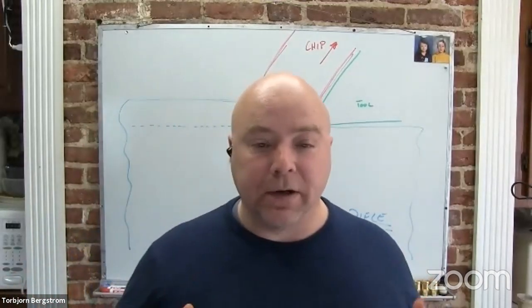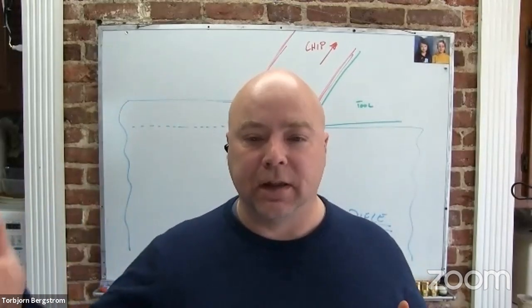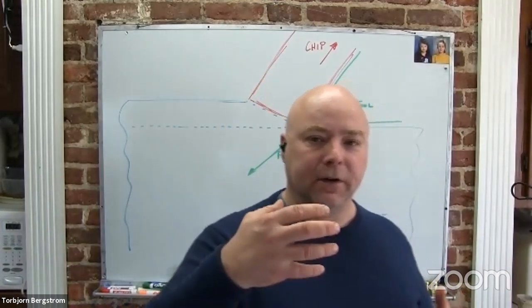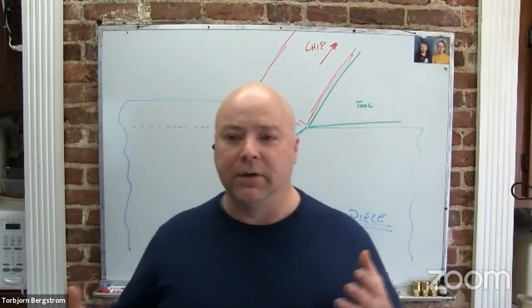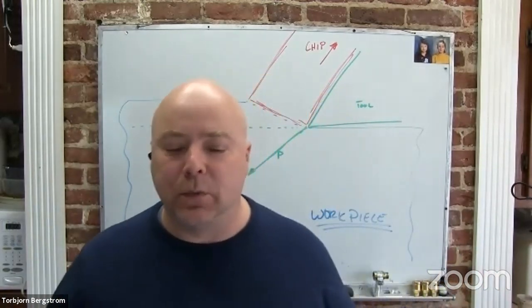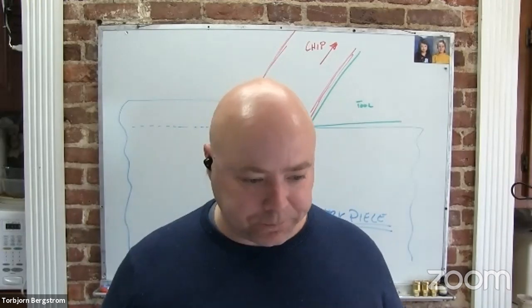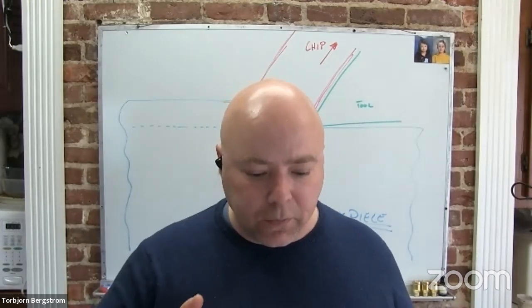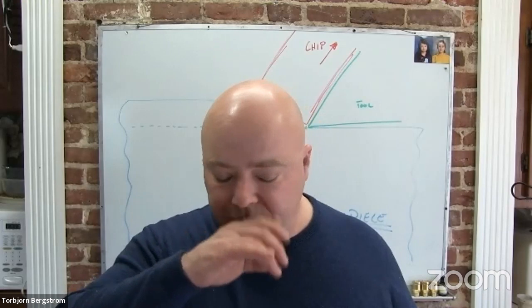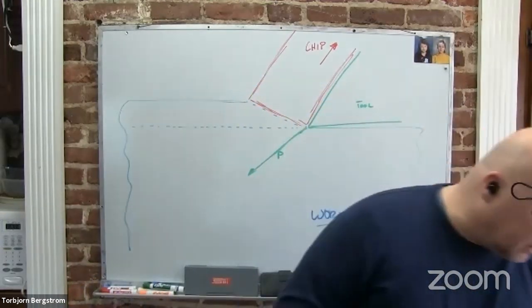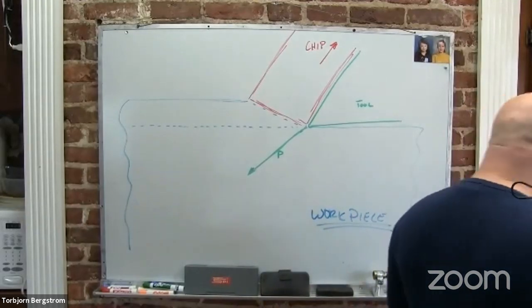Or you could measure the cutting force and the velocity or the surface speed, and you could calculate the power based on that. So those are two pretty easy ways that we could measure power with our CNC machining. Okay, so why did we care again about measuring power? I remember we cared about measuring power, but I don't remember why.